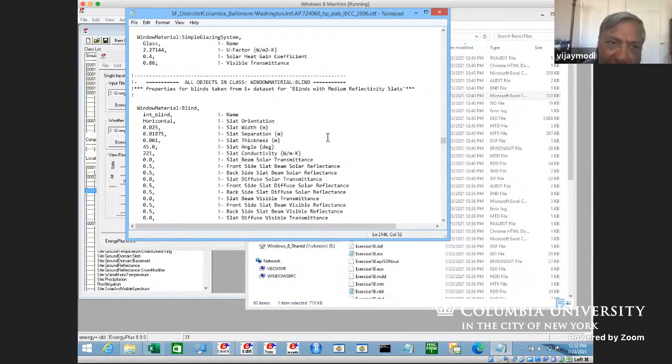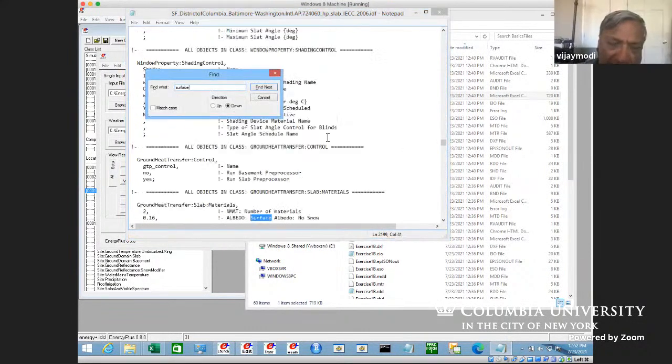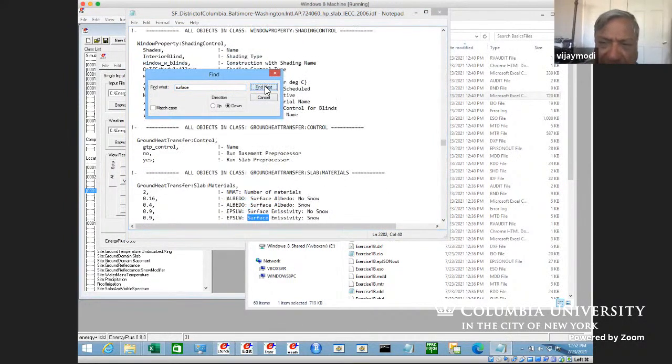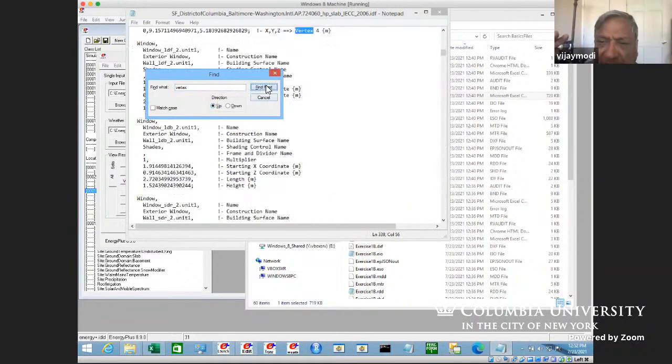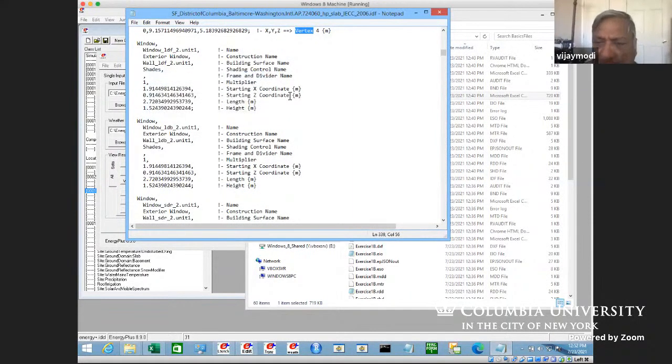Let me just clarify. Let's say there are 4 zones, and let's say you had this exact same 500 square feet, but 4 of them stacked one on top of another, and there was a vertical duct going up. As far as EnergyPlus is concerned, all you need to do is say in each of those zones, what the capacities are and all coming in. You don't need to worry about saying there's actually a common duct going from bottom to top.